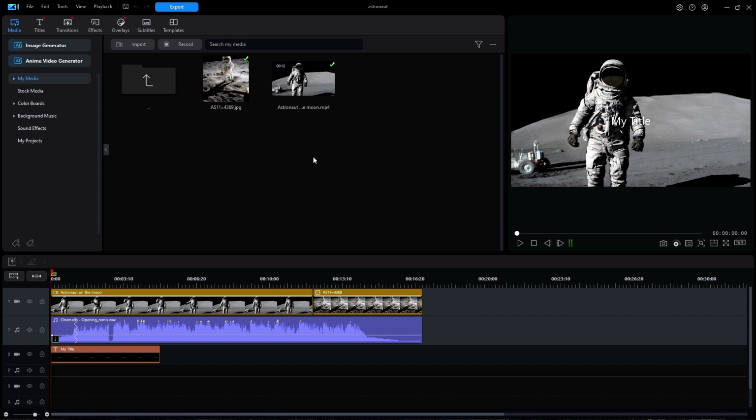Now notice that the PDS file loaded the altered WAV file on the timeline and not the original MP3. It also loaded the JPEG, which resided in a different folder. Even if you have files used on the timeline that are all from different folders, the PDS file will be able to reload your project as long as you haven't renamed, deleted, or moved any of those files.